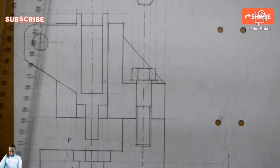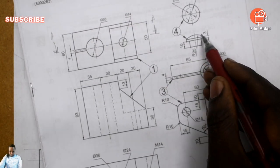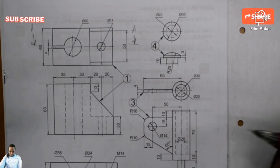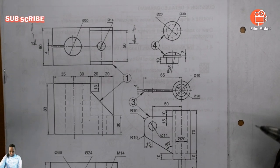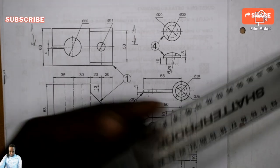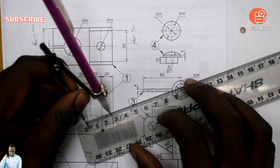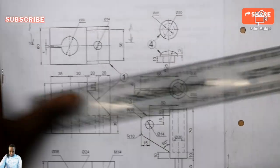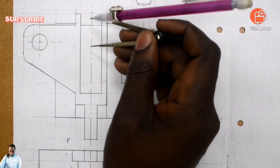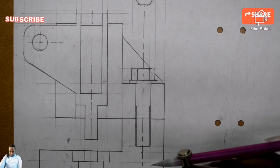You understand? So we are told, let's go back. How about this arc? We are told, please use radius 25. So how? By taking a drawing compass, open it to 25, and you place it along your vertical center line. There you go. This is my 25 on it. Then from there, I come and place it along this vertical center line.